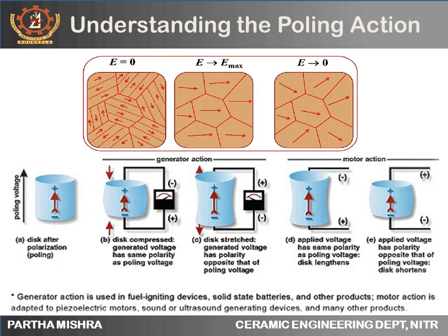In this figure below, we have a piezoelectric disc. In figures B and C, there is a direct piezoelectric effect leading to the generation of electricity when the disc is compressed, and hence a generation action. And in figures D and E, as an electric potential is applied to the same material, it undergoes a mechanical strain, which is the converse of the piezoelectric effect, and it is like a motor or mechanical action. Both the effects are extremely useful in a diverse range of applications.